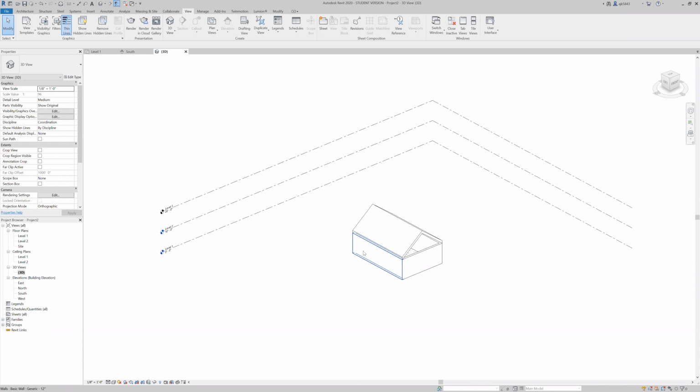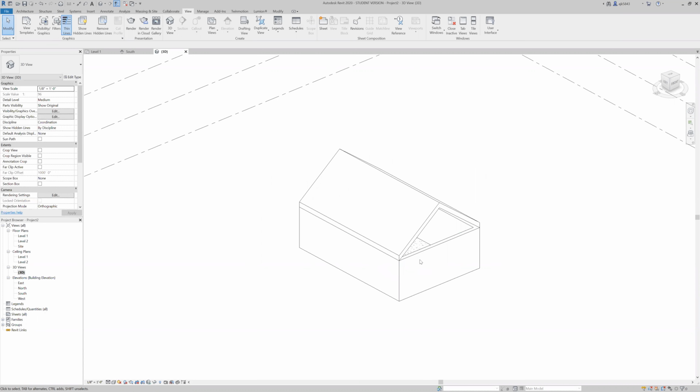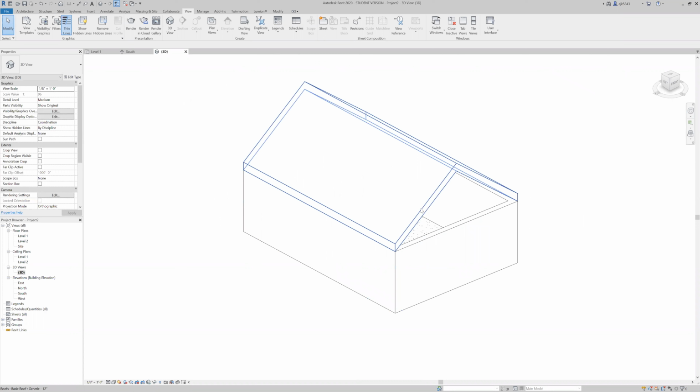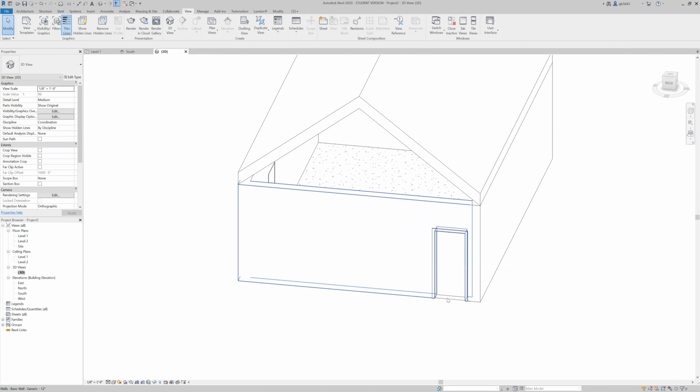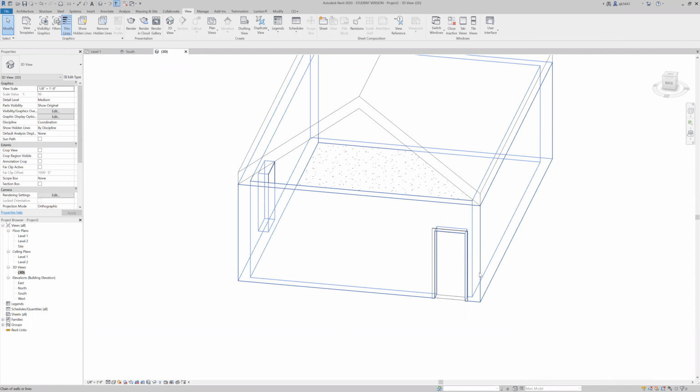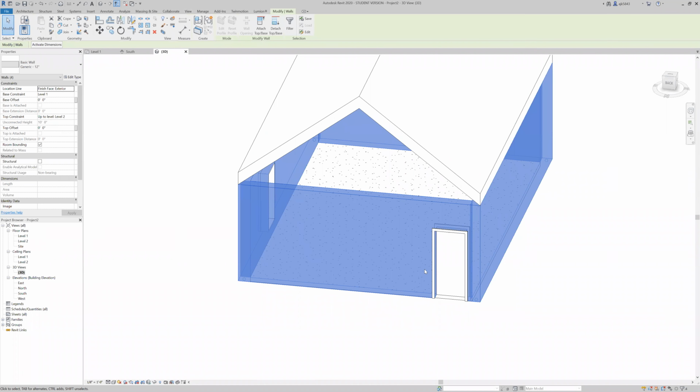Generally in Revit, whenever you're trying to select something, whatever you're hovering over with your cursor will turn blue. If there's something tricky that you're trying to get, like let's say I don't want this wall, but I'm trying to get the edge of that floor, the best option in Revit is to click the Tab key on your keyboard and that will cycle through all of the options that you can select, making it much easier to grab something that might be a little peskier to get, such as a door or a wall. Working through the tab function will also select groupings of objects, such as being able to select all 4 walls at the same time.